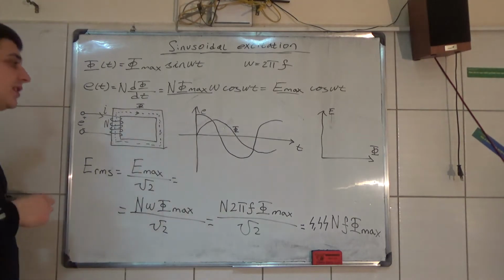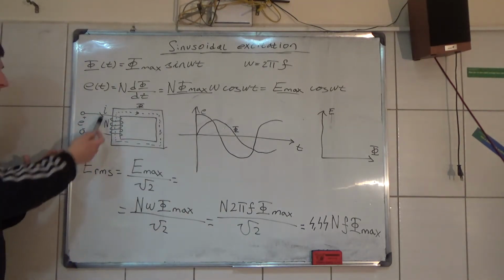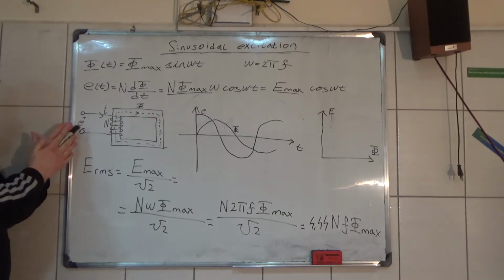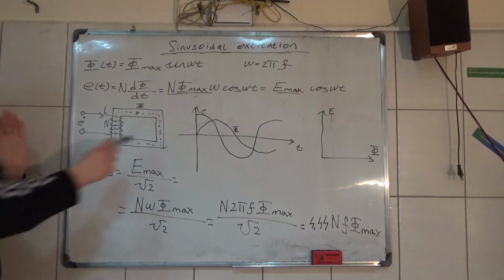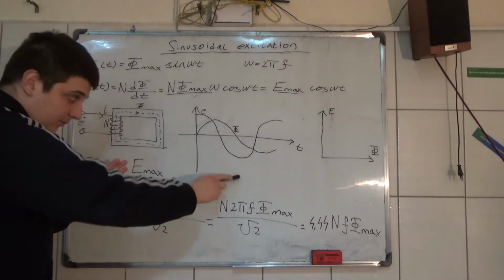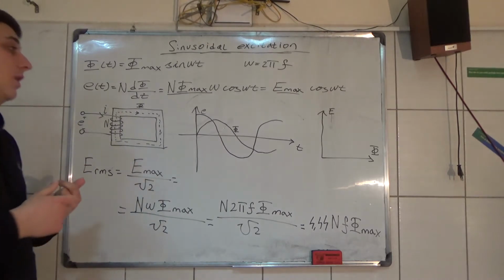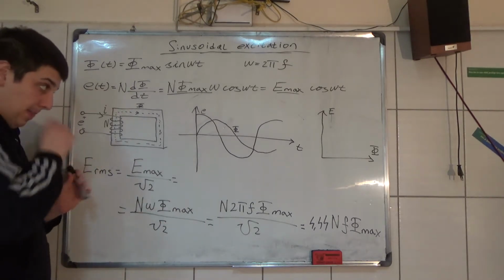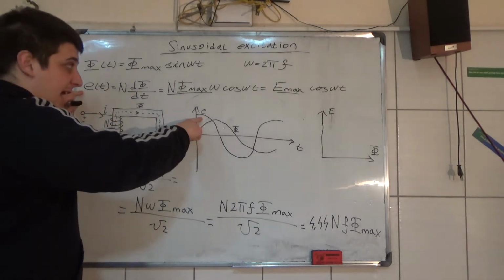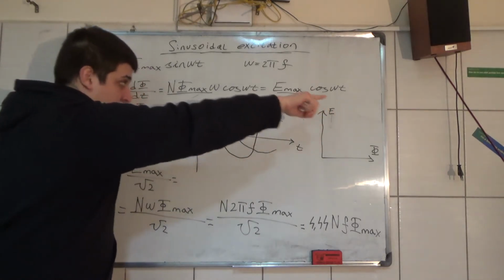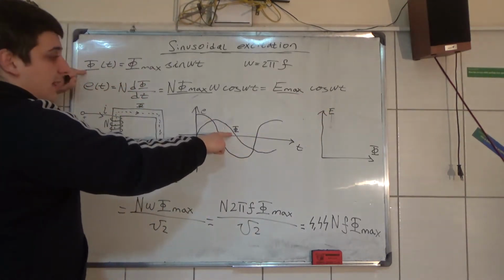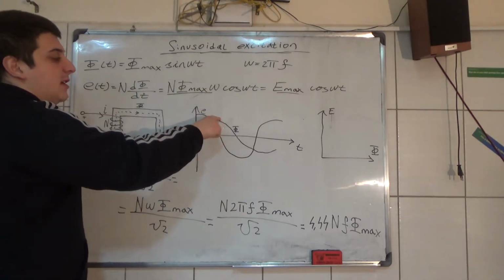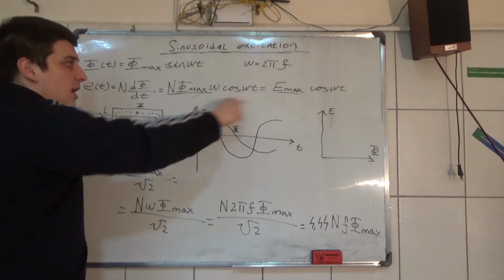So now, as you can see, if we have a magnetic circuit here, and a flux in sine omega t, here is the graphical representation of how it changes through time. The induced EMF acts by the cosine omega t, and the flux changes by time with this formula. So this is the amplitude flux maximum, and this is the amplitude E maximum.